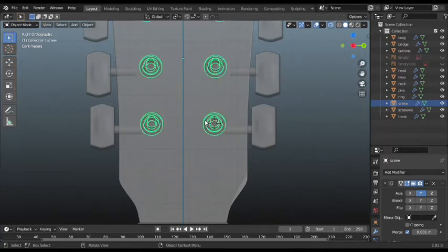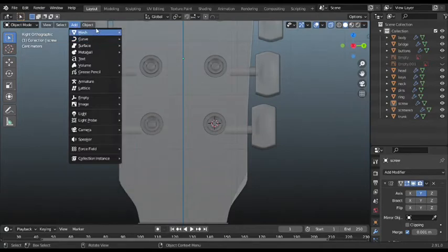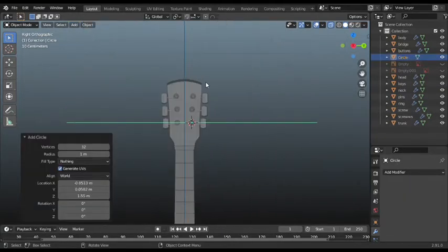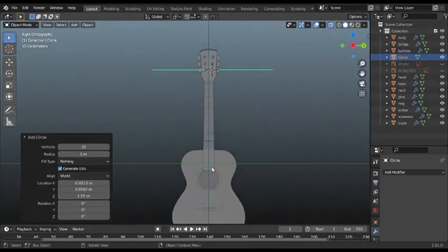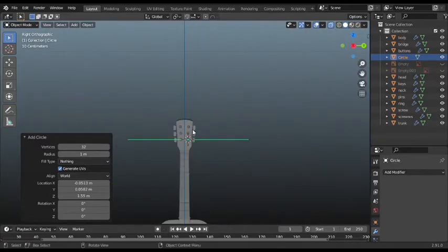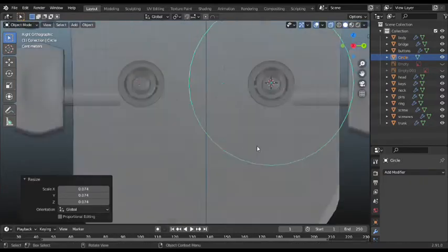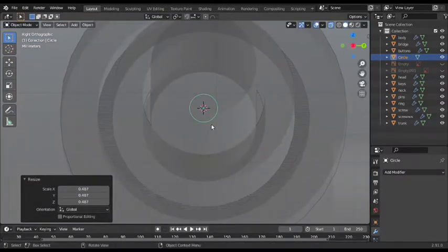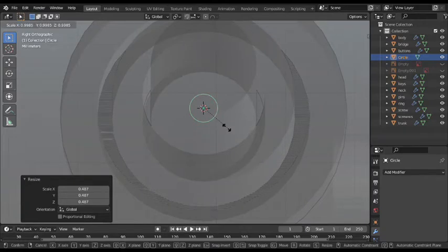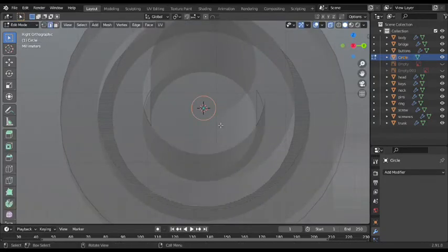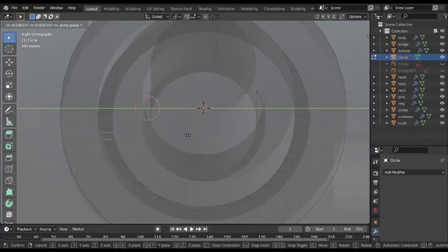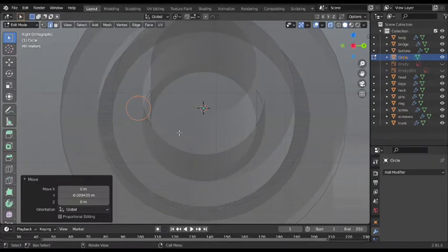So I'll switch back to the object view again so that I can add a different object now. I'll add in a mesh circle. So all you can see is previously the objects appeared up here in the center, but it's now appearing up here, maintaining the center origin point in the 3D cursor. So the basic plan is this is gonna be the cross-sectional area of the wire that I'm gonna make. Okay, so I'll press tab to go to the edit mode, select the entire circle and press G Y and move it in the diametric end of the screw.